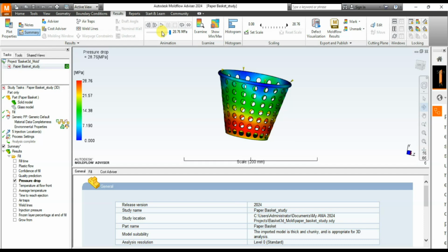Okay, so the polymer injection location. What it's simply saying is that the injection locations can also be changed. Okay, it can be flipped. Maybe like I used just the top, you can actually change in another scenario. You can swap, change, or redesign the positions of the injection locations so that the likelihood of filling the parts will be more accurate. That's what that means.